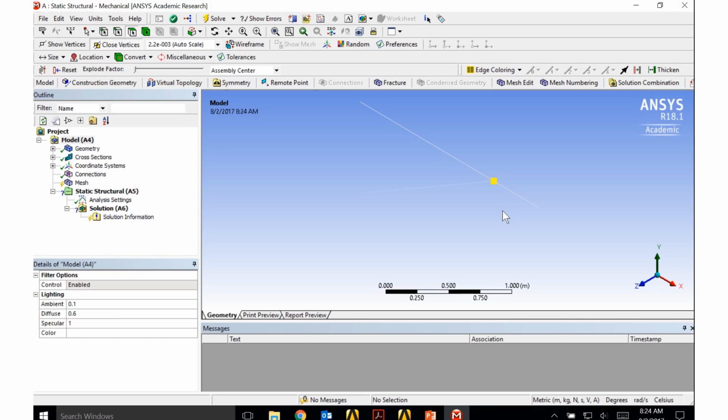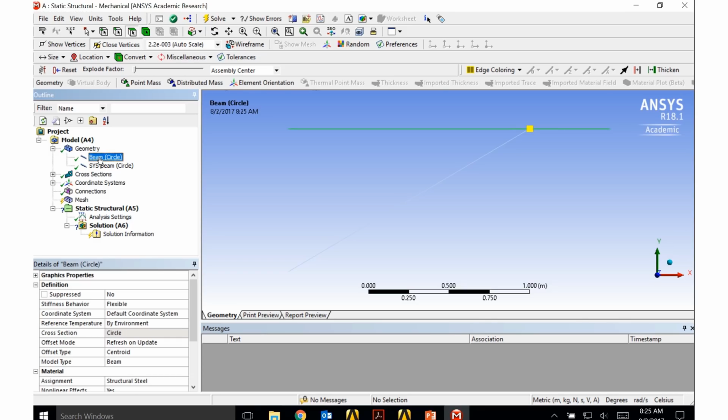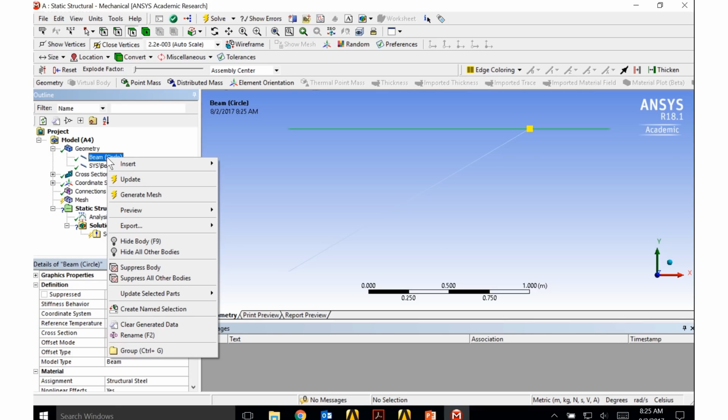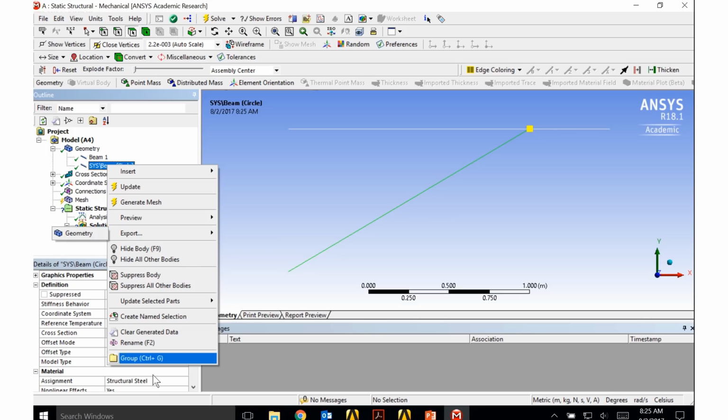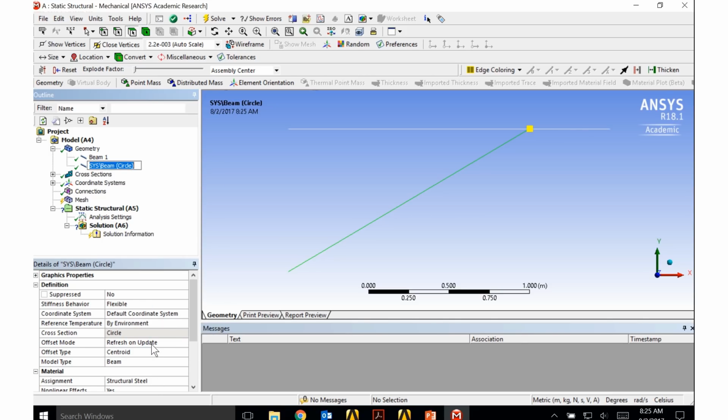So after opening ANSYS Mechanical, I can see that my geometry has been brought in. To look at it in the XY plane, I can just click on the Z arrow, and it looks good there. Graphically, I can come over and I can see my top beam and my bottom. I'm actually going to change the name on that, so I'll click it, then right click, rename, and I'm going to call this beam 1. Then I will right click on this beam member, rename, and I'm going to call this simply beam 2.